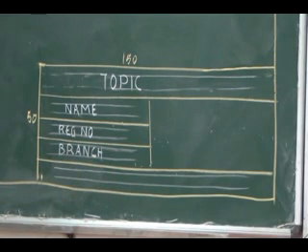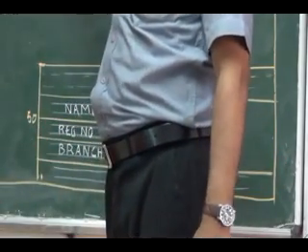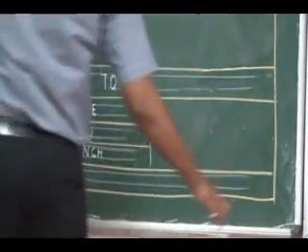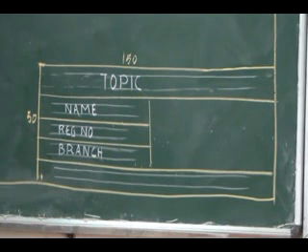The last one, you can write all dimensions are in mm. Whatever you are going to draw inside the drawing, the dimensions you will be specifying. Nearby the values, you need not specify the unit. That unit I can write here. Whatever dimensions are shown in the drawing, it will be in mm. As a common one, I can write it in the title block itself.